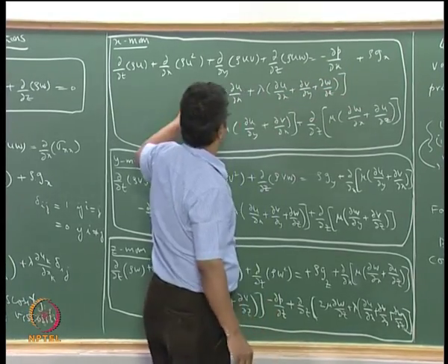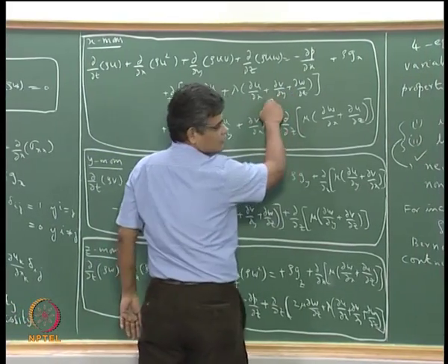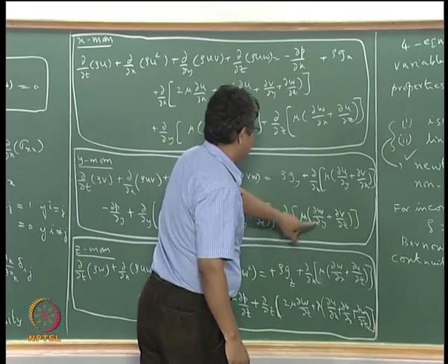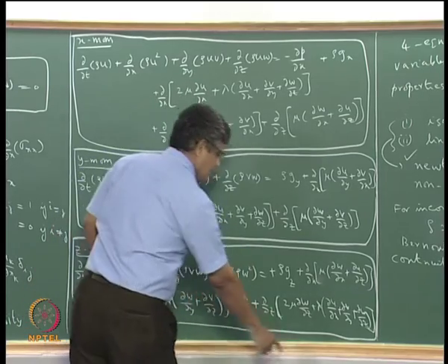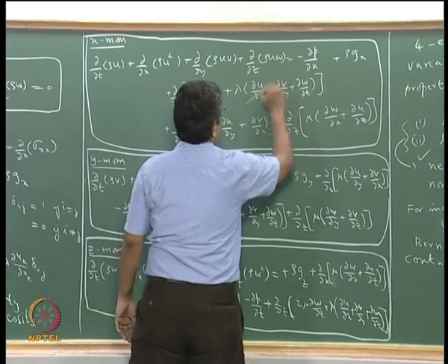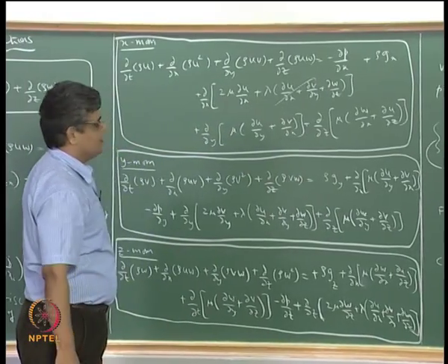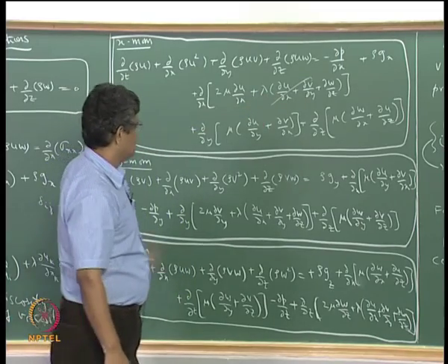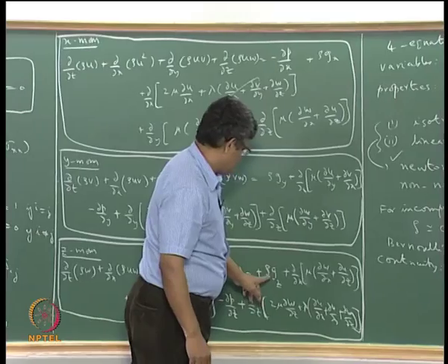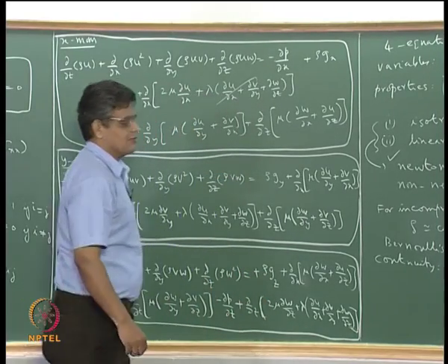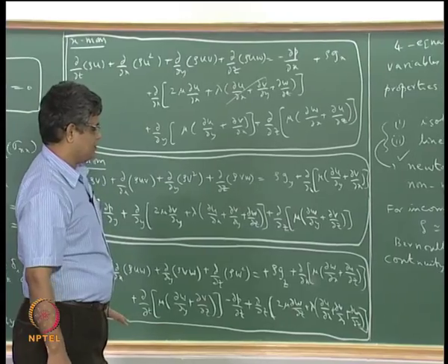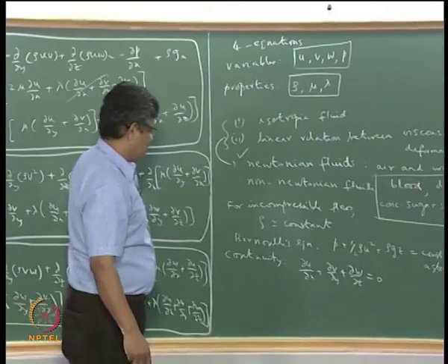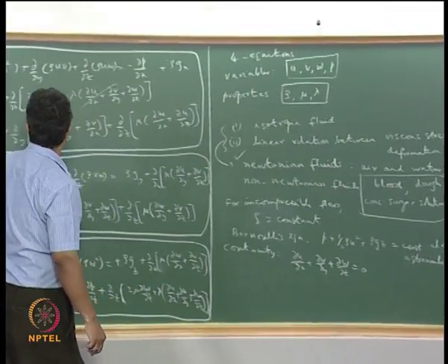This rho here cancels out, and this whole term becomes 0 because of the continuity equation, and again here it becomes 0 and here it becomes 0. Therefore, the fluid property lambda is not necessary. Okay, so we need only two fluid properties, which are rho and the viscosity, each of which is very easily measurable, and we can show that under the condition of incompressible flow with the continuity equation becoming like this,